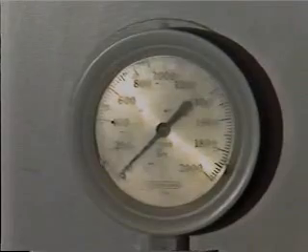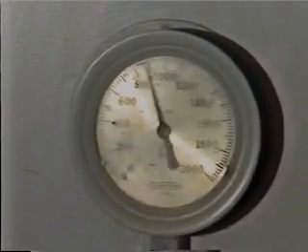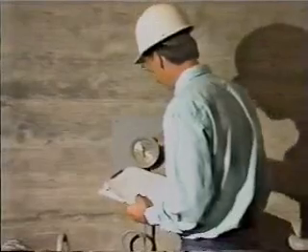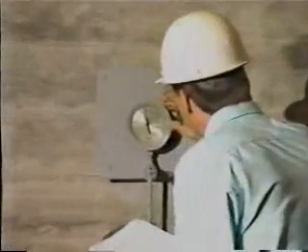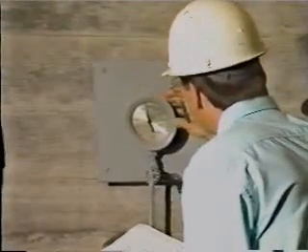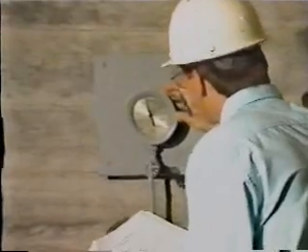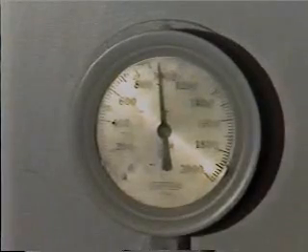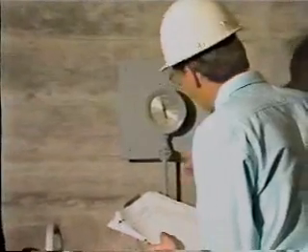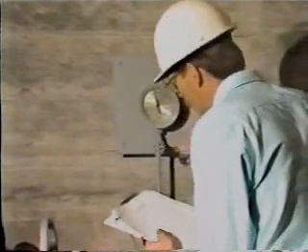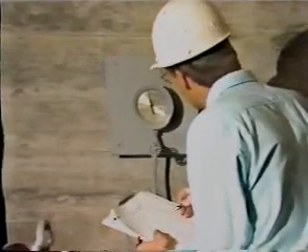Once you've finished your visual inspection, ask that the gate be lowered and, if possible, re-watered so that it will be under maximum reservoir head for the test operation. When the operator is powered up and after it stabilizes, check the amount of working pressure to see that it's within the specified pressures. Operating pressures can be found in the standard operating procedures or in drawings and manuals for the dam.